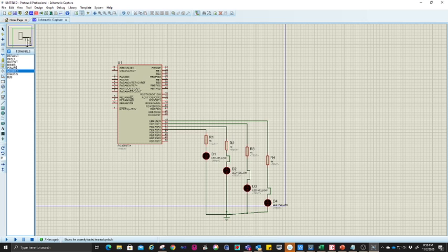To draw a switch, you must have power. This is a 5-volt switch, right? So you have the resistors here. You go back to this one, resistors. So this is the one. And then you have to connect RB2 directly to 5-volt. So the input now is always 5-volt if you do not have ground. So you have to put a ground over here, before the resistor.